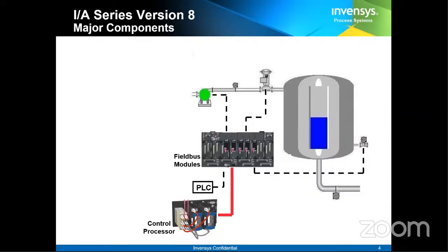These constant values may not be the same for every control loop. Based on the control loop, these values will change. So as a process engineer or automation engineer, you need to tune it. The better you are with the usage of PID, the better you will be able to tune the loop and bring the value near the set point faster.